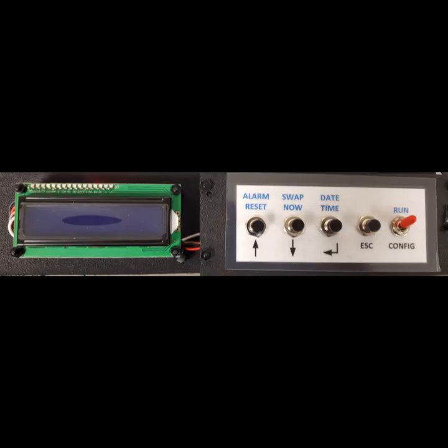The ACO is very easy to configure using buttons and an LCD display on the inside of the front panel. No computer is needed. The blue button text above the buttons describes their function when the Run Config switch is in run. The black arrows and text below the buttons describe their functions when the Run Config switch is in config. The Run Config switch should only be in the config position while actually configuring the unit or to check when the next unit rotation is scheduled to take place.